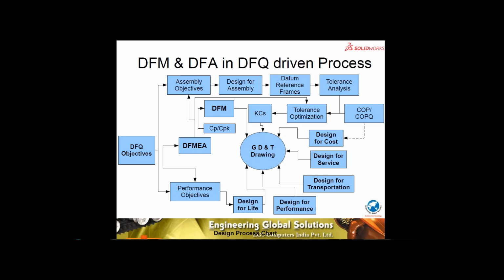For shifted processes, for depleted processes, for best-in-class processes, based on the CP/CPK, the tolerances and their effects on the part and the assembly quality can be checked up front. In other words, the overall product development cycle time comes down because more emphasis is now put on the design.